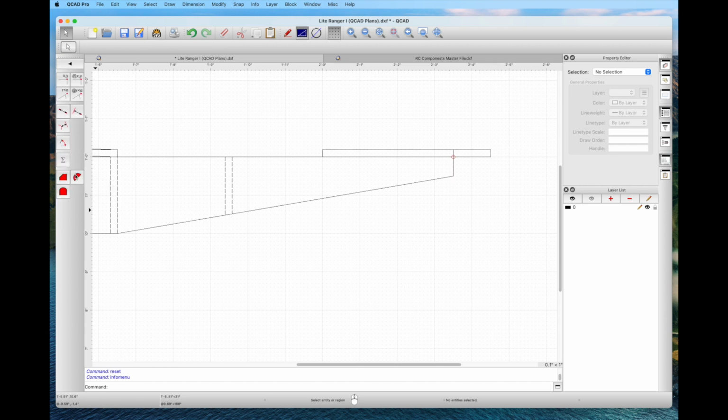The measurement tools are always good just to take a check to see how things are going along. It picks up the intersection and we can see that it's 3.5 inches long, so that's a good thing. Check your drawings as you go along to make sure the measurements are matching up to what you intended to do.